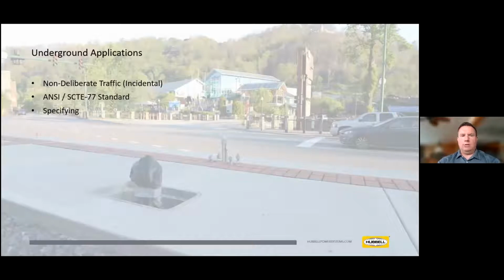For our underground applications, the vast majority of our products are meant for non-deliberate traffic applications or incidental traffic applications. Hopefully on this slide, you see a silhouetted background, and what you're seeing is a pull box embedded in a sidewalk. This sidewalk is actually elevated off of the street level. You can see that this pull box has stub ups that are going to eventually be feeding a street lighting tower right here. So that's the general application that we have for all of our underground vaults and pull boxes. They're meant for non-deliberate traffic applications. Yes, a car could bounce up onto this sidewalk, clip the street light, possibly run over the box, but that's what's meant by incidental. It's not directly into a roadway.